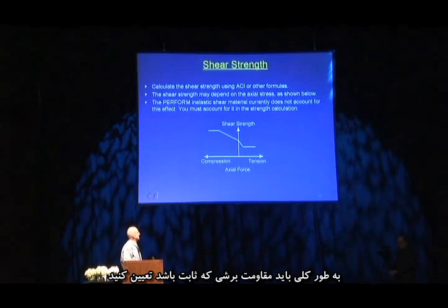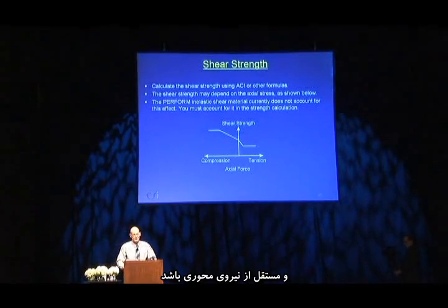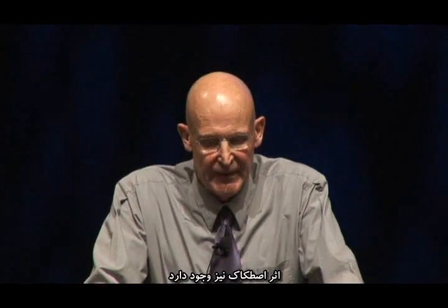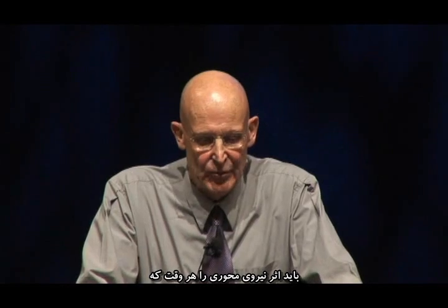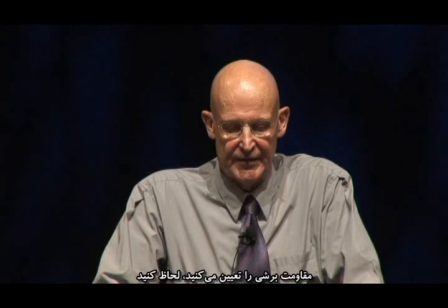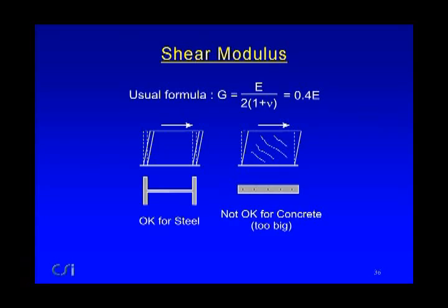Basically, you have to specify the shear strength, and it's assumed to be constant and independent of the axial force. And that's mainly because the effect tends to be like a frictional effect, and it's extraordinarily difficult to get it to work reliably when you have friction. Friction is very complicated. So in the present inelastic shear material in Perform, you have to take into account the axial force at the time you specify the shear strength. Perform will not automatically vary the shear strength for you based on the axial force.